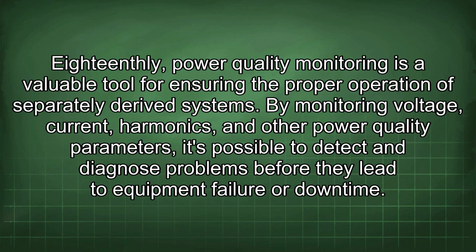Eighteenthly, power quality monitoring is a valuable tool for ensuring the proper operation of separately derived systems. By monitoring voltage, current, harmonics, and other power quality parameters, it's possible to detect and diagnose problems before they lead to equipment failure or downtime.